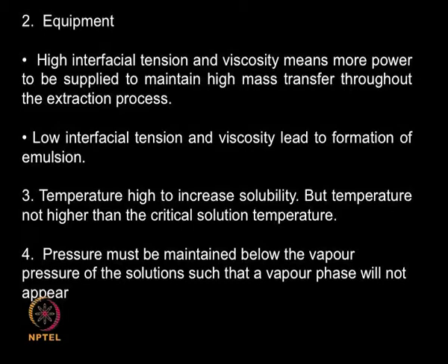This happens if you are using a very low boiling solvent. If I am using say pentane, or a very low boiling hydrocarbon, you may have the hydrocarbon both in the liquid and the vapor phase. So, some of the hydrocarbon will be lost, and you also have to think about the flammability issues. So, pressure is very important if you are dealing with low boiling solvents.